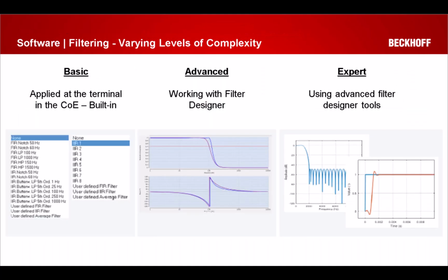So first, starting out and earlier in the hardware details, the mention of filtration was possible on board with Beckhoff's measurement terminals. The implementation of signal filtration ranges from basic selectable filters on the left here for maybe commissioning or some basic noise with a couple notch filters.